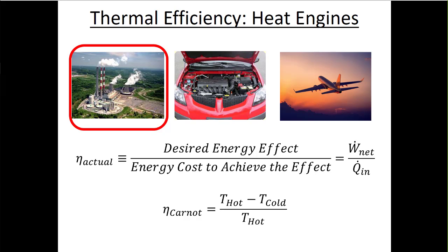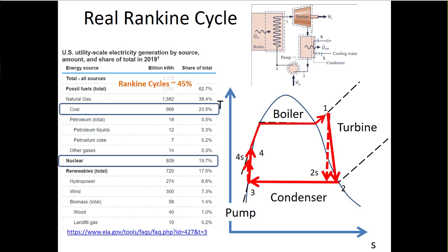You need to use Kelvin or Rankine. So when people ask what's a common mistake people make on exams: not converting to absolute temperatures in equations that have temperatures that stand alone, that don't have temperature differences, is a super common way that people make mistakes on these exams.